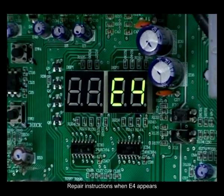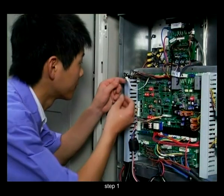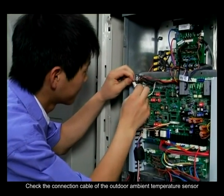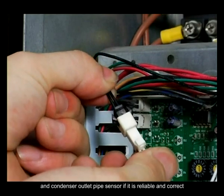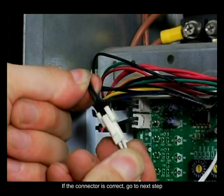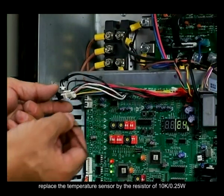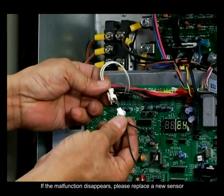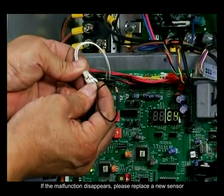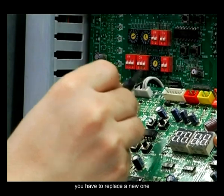Repair instructions when E4 appears. Step 1. Check the connection cable of the outdoor ambient temperature sensor and condenser outlet pipe sensor to see if it is reliable and correct. If the connector is correct, go to the next step. Step 2. Replace the temperature sensor with a resistor of 10K, 0.25 watts. If the malfunction disappears, please replace with a new sensor. Otherwise, the PC board of the outdoor unit should be broken. You have to replace a new one.